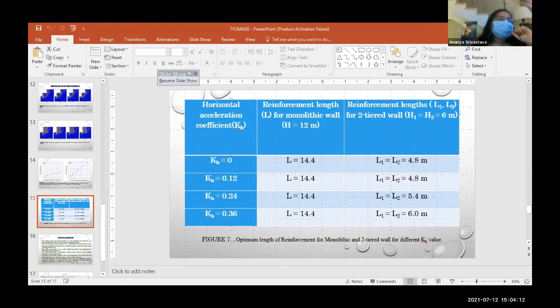Sir, whenever I'm talking about an MSE wall, again, I would say it is totally at the discretion of the designer whether you construct a monolithic wall or a two-tiered wall system. Suppose you have a hilly area with a rock bed formation. Would excavation of a rock bed be easy, or is such deep excavation possible when you're constructing a very tall wall? You would require more manpower and more energy, again increasing your footprint. Instead, if I construct a tiered wall system, whether two-tiered, three-tiered, or multi-tiered, we would require a little less effort, whereas the tiered wall system gives similar beneficial results.